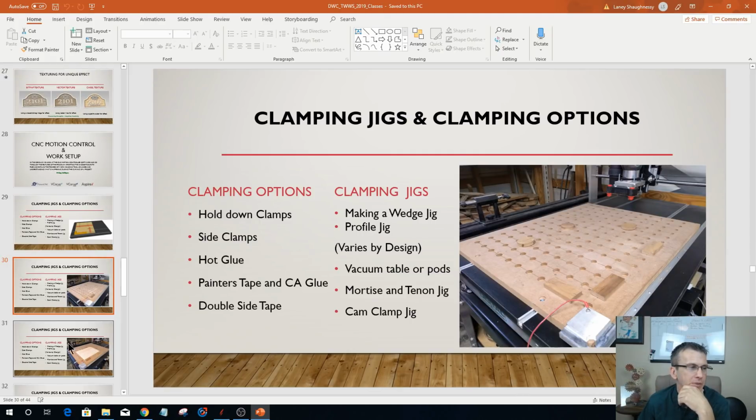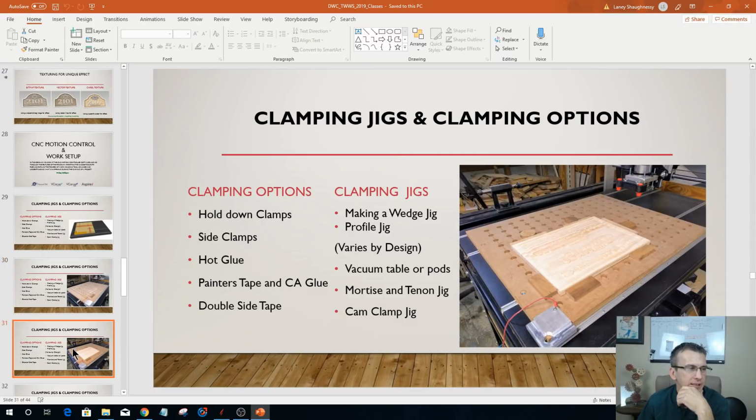I've got 3 cams so that when I'm clamping my material, I can cam lock that material into place. So basically it's just an MDF wasteboard with holes that are 3/4 inches in diameter, 3/8 of an inch deep, set 2 inches apart on center.